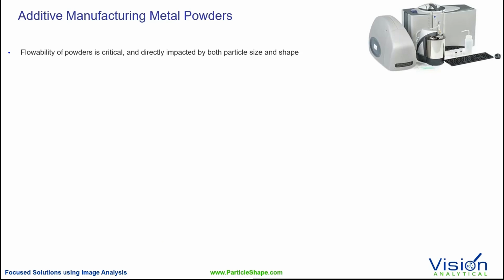Metal powders are actually something that's being used quite a bit these days in the additive manufacturing world. There are different types of metal powders, and the selection of the metal powder really is dependent on the application. These metal powders generally are very round in nature and have a specific size, and that's a requirement, not only due to the flow pattern of the nozzle that is depositing the powders, but also for the compactability and deposition of the particles where the metal particles get fused.